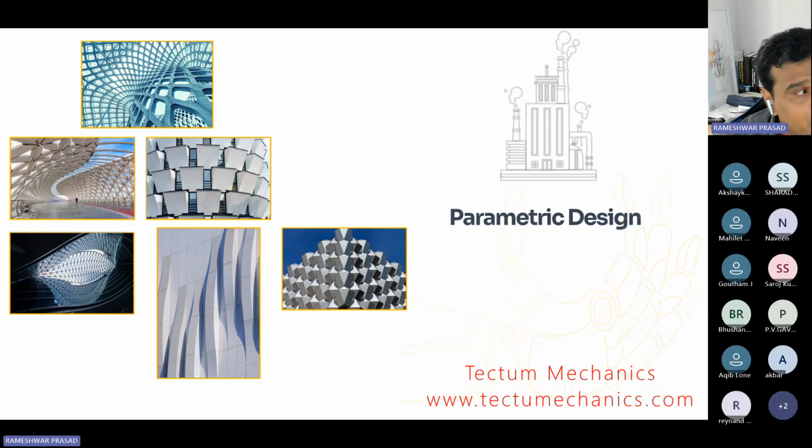First, because of the physical limitations imposed by the vendor drawing or the mechanical drawing or the piping layout and so on. Also, the loads that a typical structure is subjected to are quite varied. You have dead load, live load, wind load, seismic load, anchor load, guide load, and so on. That's why you have multiple load combinations, and trying to fit in every load combination can be quite laborious in generative design. Algorithmic design doesn't really fit the bill either, right?